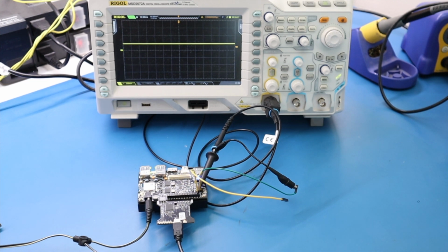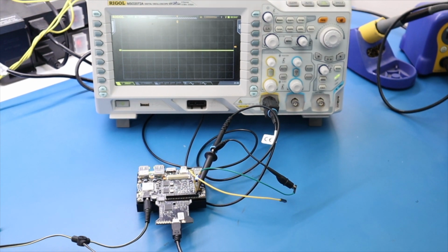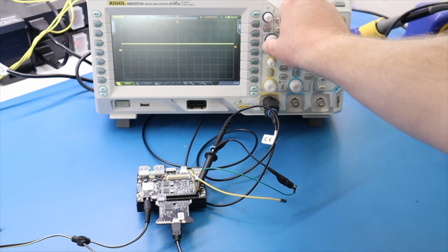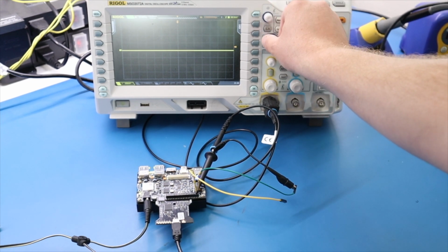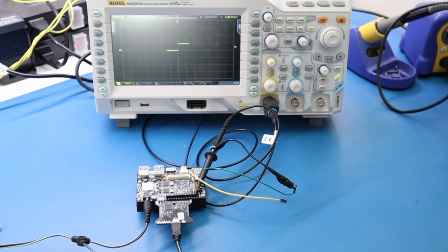Okay, so I've got this hooked up to my Rigol MSO 2027A, and you'll notice that it's flopping back and forth, but it looks like it's taking a really long time. The idea of that is so that we can actually see the LED turn on and off. So you're going to have to zoom right in on the time scale so that we can see roughly a second in total time. We'll give it a second to catch up, and you'll see it'll draw it out. So that pin is actually turning on and off. Like I said, it's just a 1.8 volt pin.